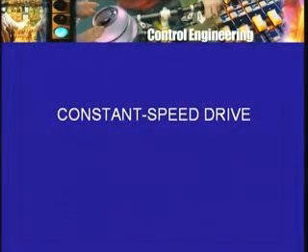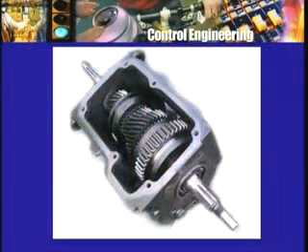However, the IC engine, the engine which is the source, prefers to run at more or less a constant speed. That's one of the features of a petrol engine or a diesel engine. It's not that it has to run at a constant speed, but varying the engine speed itself directly is much more difficult. So we'll have the engine running at more or less the same speed, but the drive shaft or the car speed is going to change, and this you achieve with the help of the gear train or the gearbox of the motor car or of the scooter.